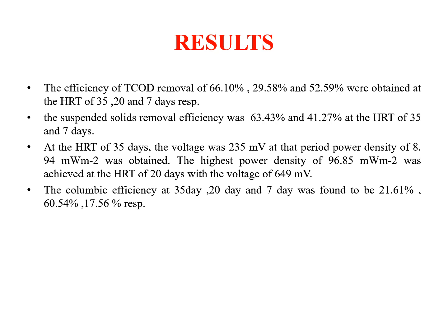At the hydraulic retention time of 35 days, the voltage was 235 millivolts. At that period, a power density of 8.94 milliwatt per meter square was obtained. The highest power density of 96.85 milliwatt per meter square was achieved at the hydraulic retention time of 20 days with the voltage of 649 millivolts.